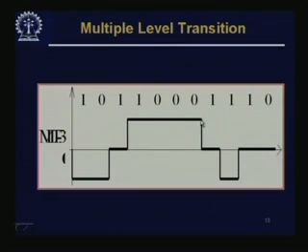Then from 0 to 1, now from high, since the 1 has come, you have to come to low, and again another 1 has come, you are going in the downward direction, so we continue from 0 to low, and then another 1 from low to high, and then 0, there is no transition. So this is the way MLT encodes using multiple levels of signal. This reduces the net analog bandwidth requirement for the cable. So this is how a tenfold increase in the speed was achieved on the same physical infrastructure.